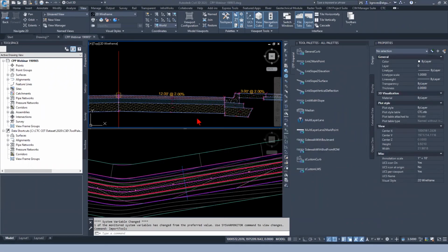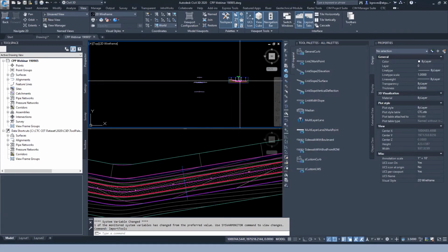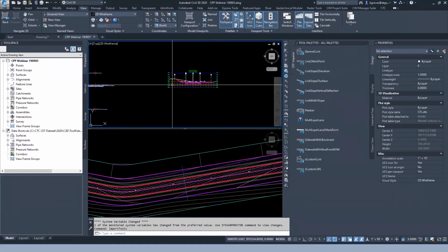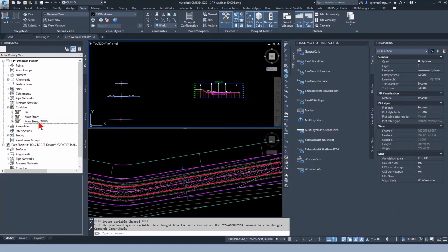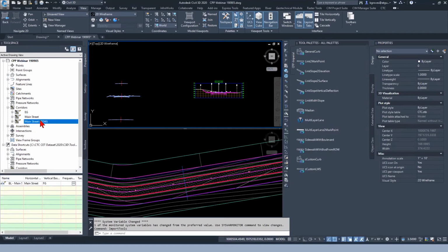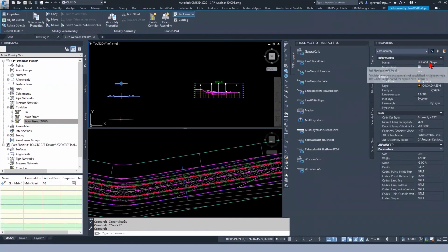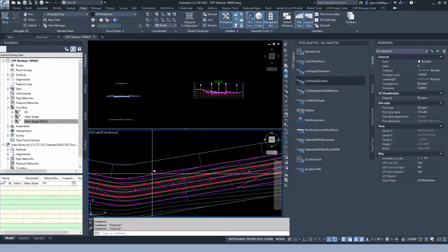Stephen Boyd wanted to know, how does my corridor know to match my existing ground at the right-of-way? So I did two things with this, Steve. First up is I created a whole separate corridor. I called it whatever right-of-way. So it's still using that same baseline as my main corridor is, but it's just defined with a link, width, and slope subassembly.